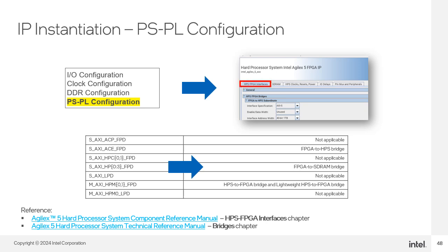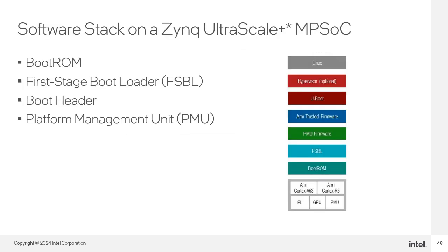Here is a mapping of the interfaces available in the Zynq PS, with their equivalent bridge interfaces in the Agilex 5 HPS. In a Zynq UltraScale+ MPSoC device, there is a boot ROM for initial bring-up of the device.